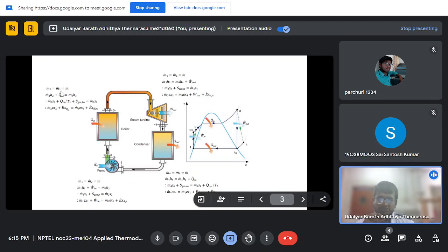You can use both the second and third equations to generate the exergy equation, the exergy balance. So we can say that the exergy coming in from the mass entering at point 2, plus the exergy with the heat transfer, equals the exergy lost in the boiler plus the exergy which is going out. So similarly, I have written similar expressions for each of the other components, and I've shown a TS diagram for a Rankine cycle.